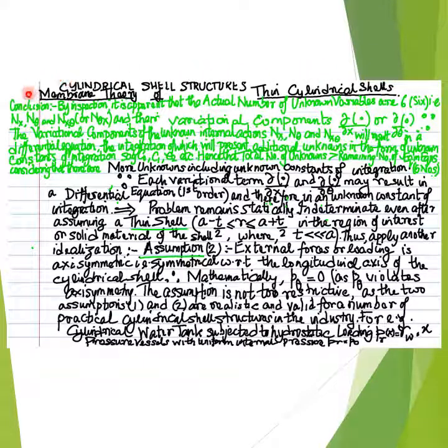On the application of the moment equilibrium equations based on the consideration of the statical moment equilibrium of the differential thin cylindrical shell element, the unknown internal out of plane shear forces qx and q theta vanished in order to satisfy the moment equilibrium equations sigma mx equal to 0 and sigma m theta equal to 0,